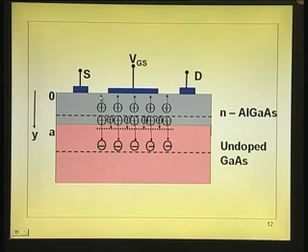See here, this portion of the depletion layer belongs to the gate. This portion of the depletion layer belongs to this PN junction. So, if I apply extra voltage, the depletion layer will move down and this depletion will collapse and the charge here will reduce. That is what we have been telling right through. Redrawing it in a neat fashion here.